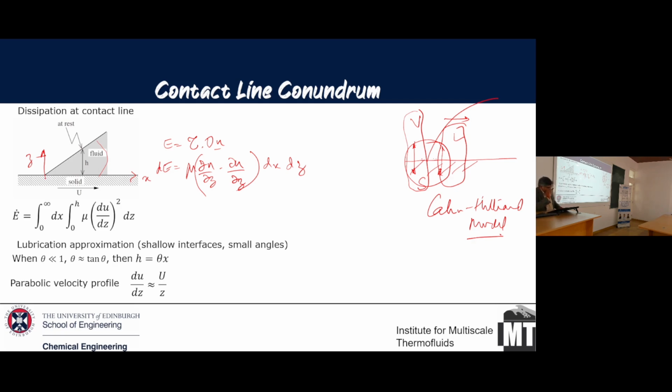Now, this is something we need to be very careful about, and many books think that the reader is able to guess this right away. This particular contact angle, in my opinion, is not the apparent contact angle. It's the inner contact angle. Because if you want the droplet to move, if you zoom this in, this guy has to move. So technically, the inner contact angle is always very small. This is the apparent contact angle, which we call the equilibrium contact angle, but this is the actual inner contact angle, which is very small.